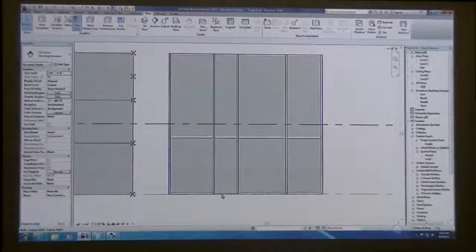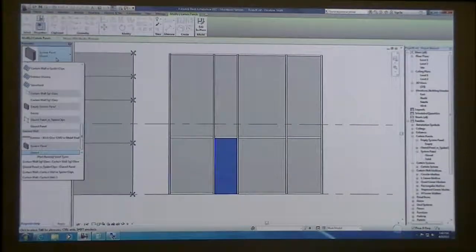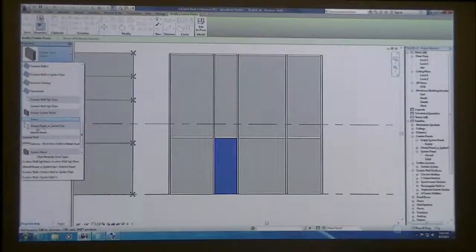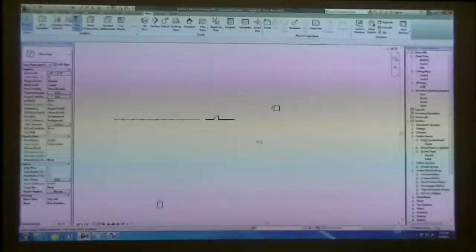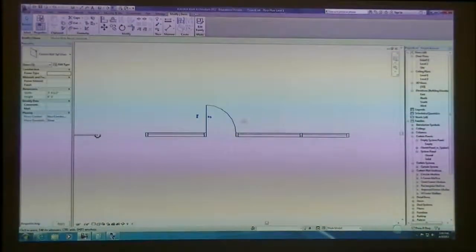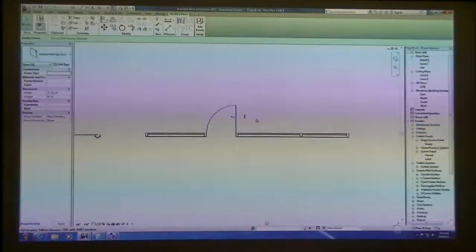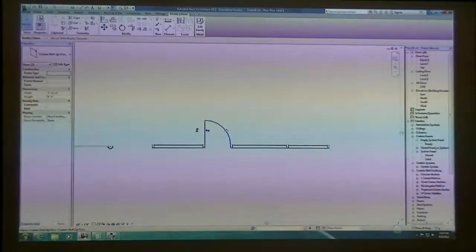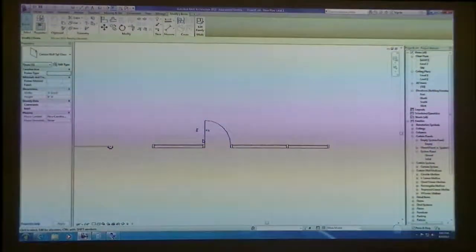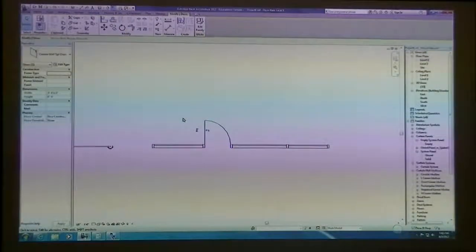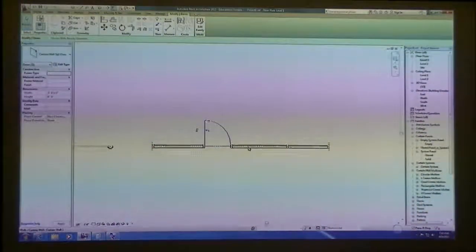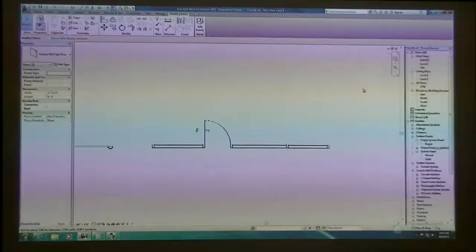And when I look at this in elevation, now that it's loaded into the project, if I tab over this system panel, I can now select from the left. You should see another, so we had our glazed panel with spider clips. We also have glazed wall single glass. I've now placed a door, and in the floor plan view, this is where you can click on it and flip and get the door swing to be in the right location. This is a door that can be tagged and scheduled, and it acts like other doors. However, it had a slightly different template that works directly with the curtain wall system. And that's why we had to use only those 3 different types of doors.